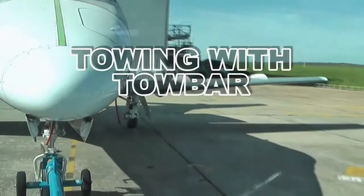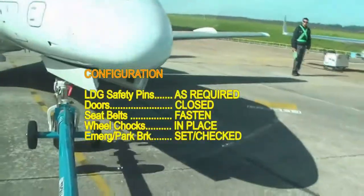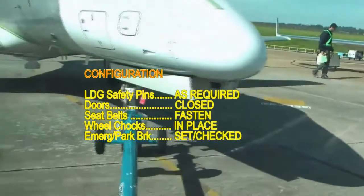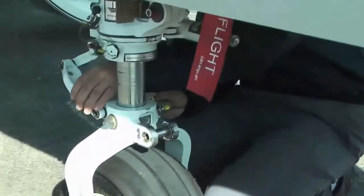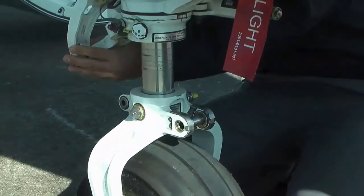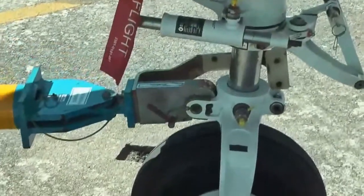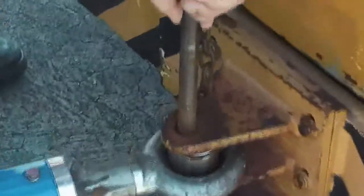Towing with tow bar. Make sure all ground equipment is removed from areas adjacent to the airplane and all external services are disconnected. Disconnect the nose landing gear torque link. Connect the tow bar on the nose landing gear. Connect the tow bar to the tractor.